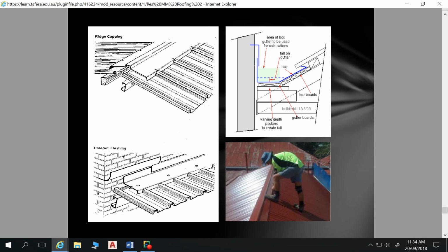Depending on your distance there, I think a flashing over the top of that is also a good idea. That's completely up to your architect to design, but that's the sort of detail I'd feel far more comfortable about, because that way your flashing is fixed really well, and all your surfaces are sloping down, facing back to your roof sheet.